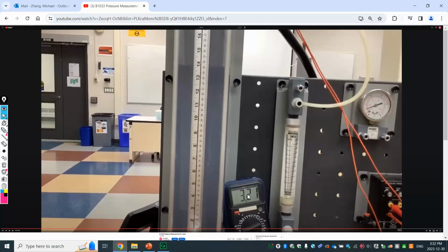In Lab 11, we start to look at this. This DMM right now shows 3.21, which maps to the current water level here. That's the target we want. As a result of the lab, we want the 10 centimeter level around here mapped to 0 volt.